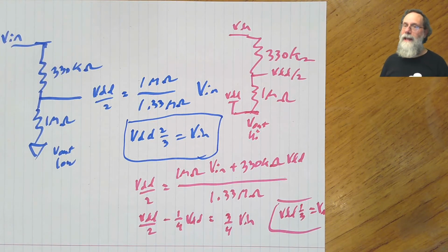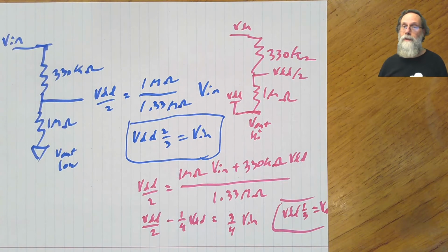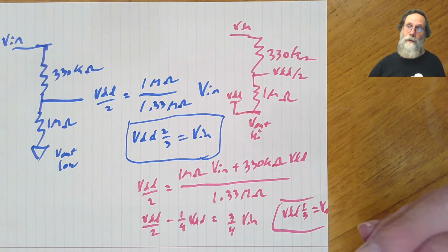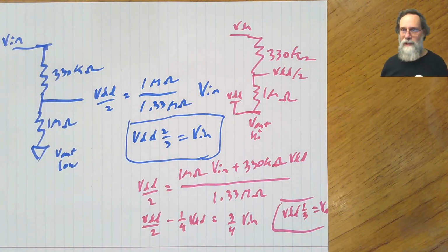If you pick that as your constant voltage for this non-inverting Schmitt trigger, then you're going to get exactly symmetric thresholds, with these two resistor values selected to give 1/3 and 2/3. By adjusting the ratio of these two resistor values, you can move those in and out.